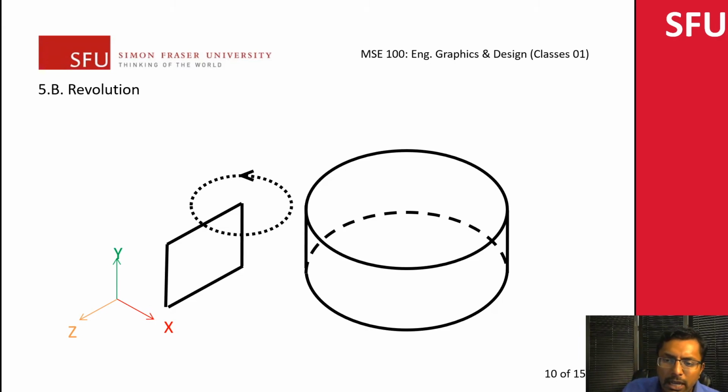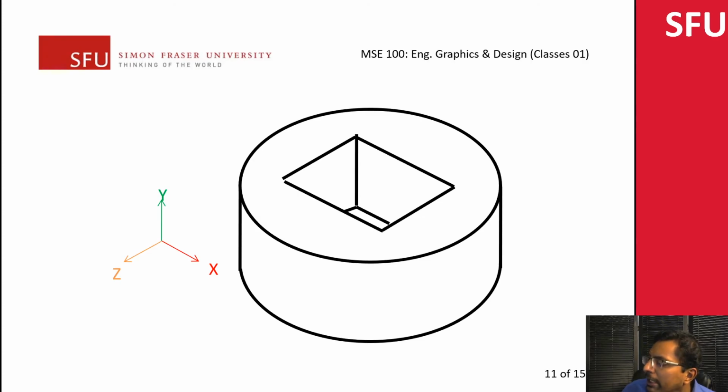In this particular case, let's see if you wanted a square hole. You can't really create a revolve and then create a square hole. So there are only a couple of ways you can do this. One is to create everything on the top plane or the XZ plane, and then you can do either an extrude or an extrude cut. The other way to do it would be to do the revolve for this particular shape and then do an extrude cut for the rectangle over here. So let's see how that might work.